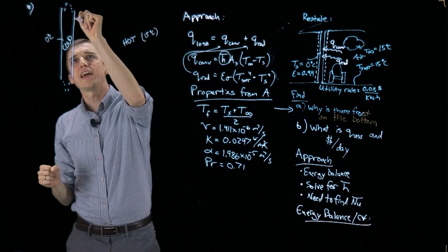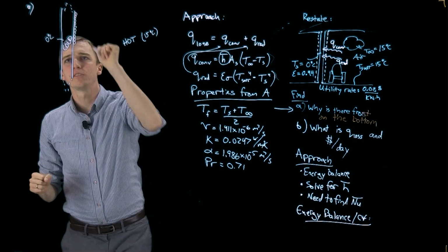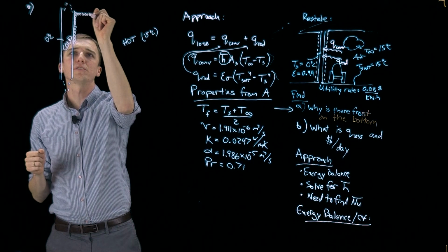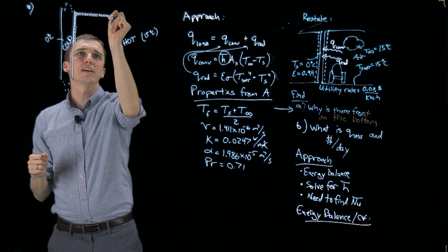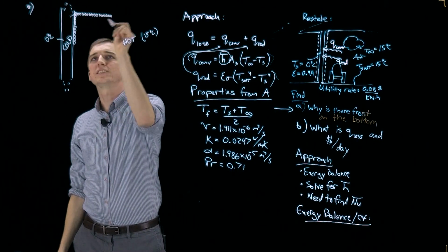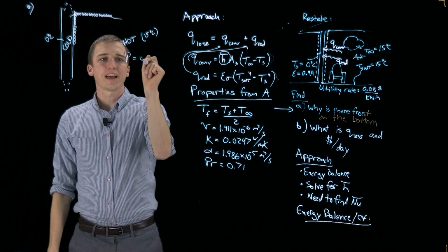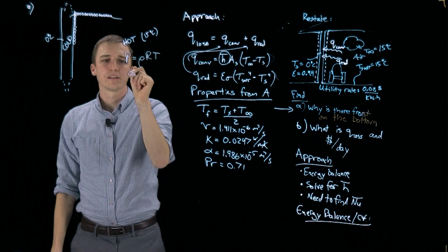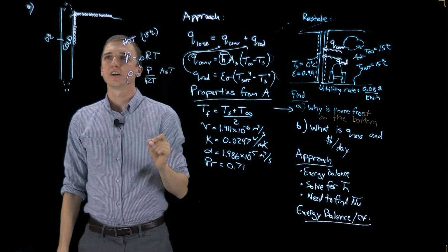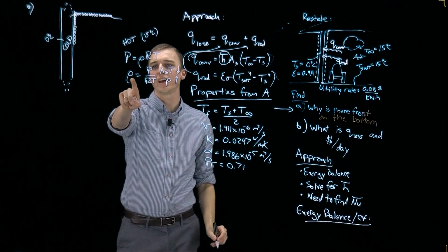What that means is that the air molecules directly touching the window are going to adopt the temperature of the window, or 0 degrees Celsius. Now, let's look at molecules approaching the bulk temperature of the air, 15 degrees C, right? So as we go out, this one is at 0, this one's at 15 degrees C. And we know that based on the ideal gas law, as we showed in class, as the temperature goes down, then the density goes up, right? As this goes down, density goes up.